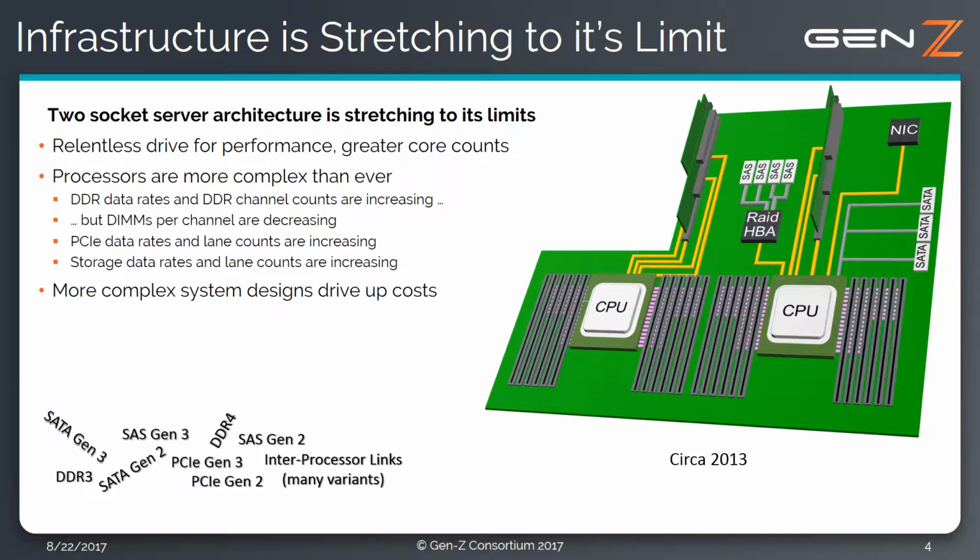One of the interesting trends that occurred with the introduction of DDR Gen 4 is the drop in the number of DIMMs per DDR channel that was typically found on servers, from 3 DIMMs per channel to 2. This was because the increased speeds and electrical challenges made it necessary to lower the DIMMs per channel, thus driving the requirement for more DDR channels per CPU socket to maintain and increase memory capacity.